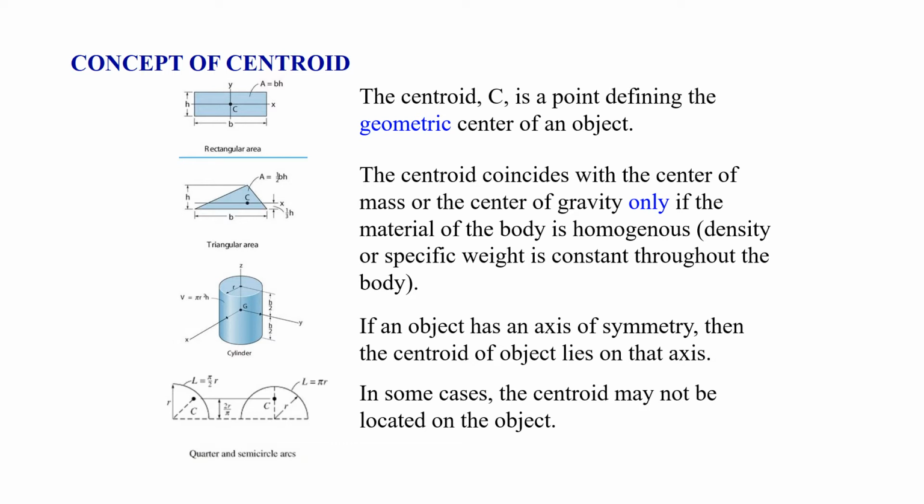That might seem a little odd, but if you remember the goalpost example in the image we had earlier, that would be a case where the centroid might very well not lie anywhere along the goalposts themselves. It's just going to be a point in space where we could represent the full weight of the goalposts.